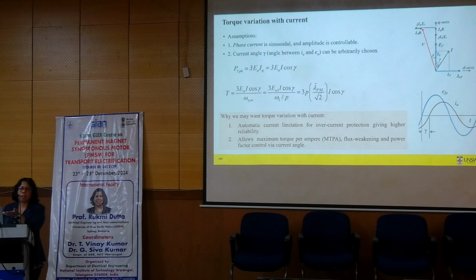Here we can also think of back EMF E times current I as your mechanical power, even in the synchronous machine, right? But because they are not DC quantities, they are AC quantities, so we have to represent them as a phasor diagram or vector diagram. I also mentioned that your back EMF is usually in your Q axis, right? And magnet flux linkage is along your D axis.